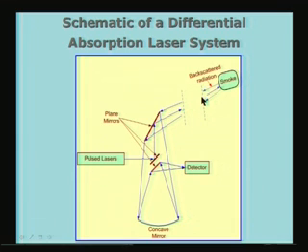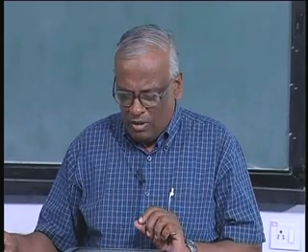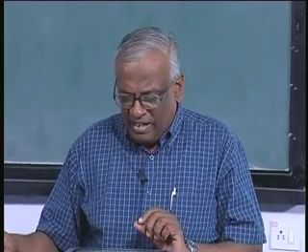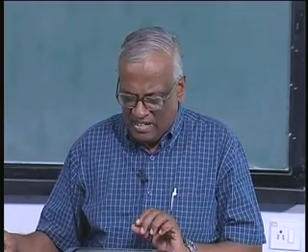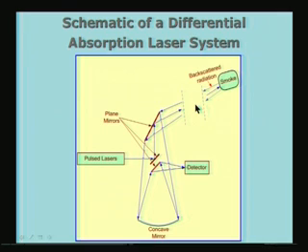So, I will choose the time delay, and also the gate, the time over which I am going to make the measurement, such that I can specifically find out what is happening in this particular region between these two dashed lines which I have shown here. Okay. So, what happens in this case, the return signal follows the forward path and it comes back